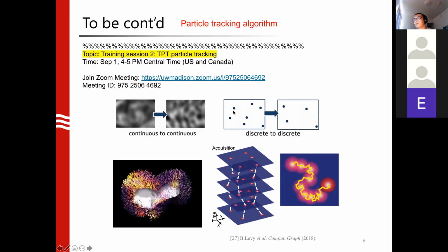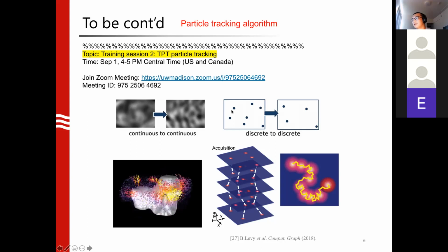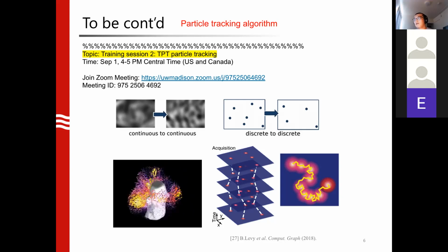If you just track an individual bead, it's called single particle tracking. If you track all of them, people call it multiple particle tracking. The tracking also gives you the same thing, the deformation field, which means the displacement field and the strain field. Their goal is the same, just that they work for different patterns, different experimental conditions, and other things.